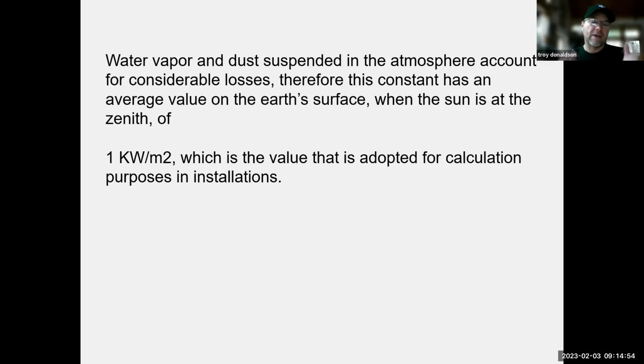Okay. And right now, I don't care if it's pointing in the correct direction. I just want you to get a feel for how much energy comes from the sun. So 250 square meters is my roof. That means I have 250 kilowatts available per hour from the sun. That's a kilowatt hour, right? So if my roof sees 4 hours of sun a day, that's 1,000 kilowatt hours a day.